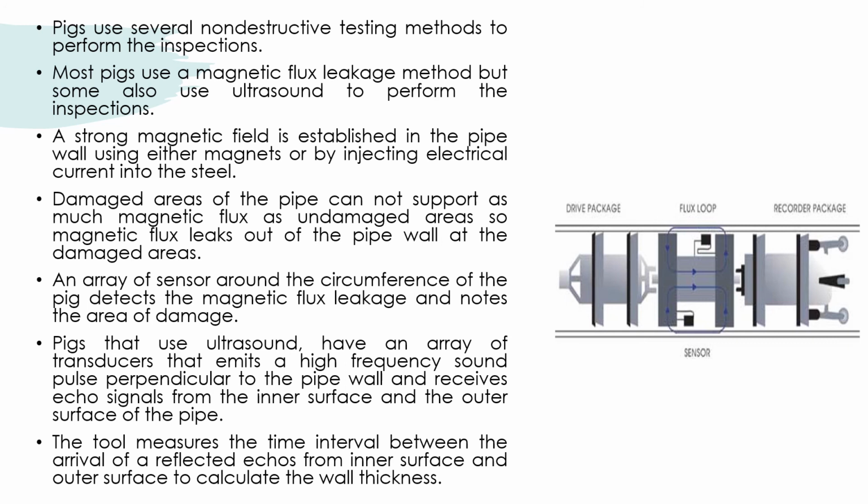A strong magnetic field is established in the pipe wall, using either magnets or by injecting electrical current into the steel.